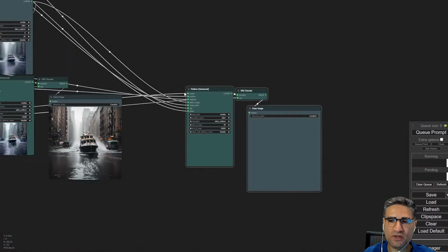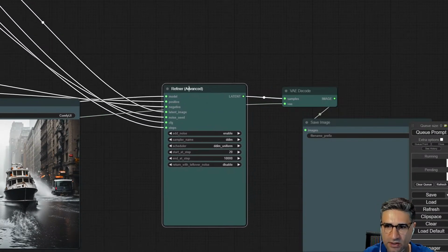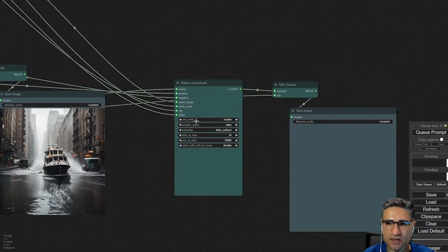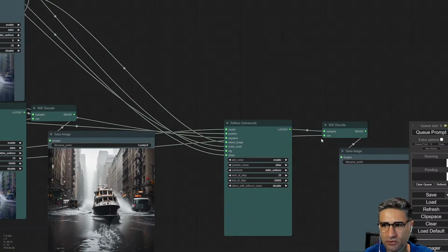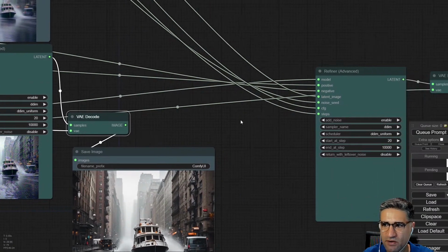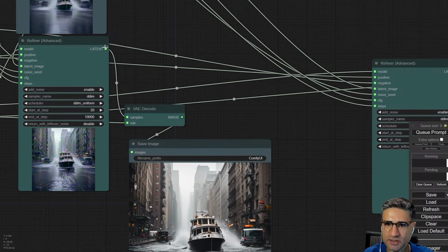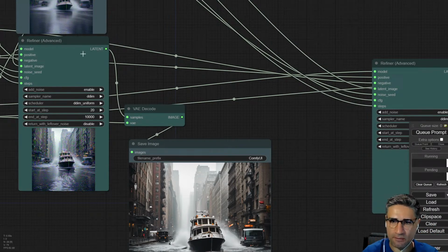In ComfyUI, when you press Control Shift V, the nodes will be pasted with the connections. So it is not necessary to connect the pipes into your sampler again. Okay, and this time I want to send the processed latent to my other latent. So from this part, I'm going to make an upscale.